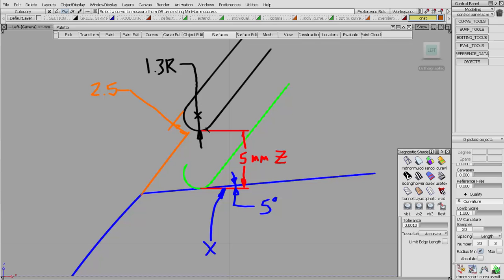And then I might need to compensate for overslam since this hood moves up and down and it's sprung at the bottom. Maybe we'd use 5 millimeters in Z of overslam. Some companies could use 10. Some companies could use 7.3. The number isn't specific. It's just a piece of criteria that you need to think about.